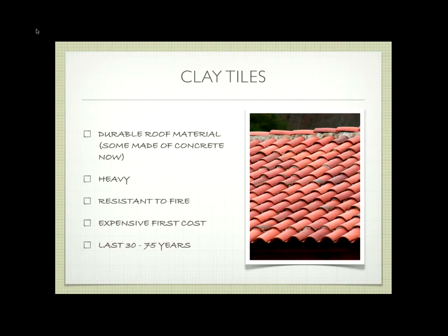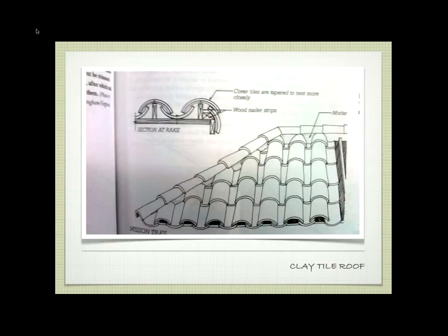They're very heavy, though, and that's something to be aware of. You have to engineer your building to withstand the loads that are there. They're resistant to fire. They are also expensive in the beginning, not as expensive as slate, certainly, but they're still more expensive than an asphalt shingle roof, for example. But they're going to last 30 to 75 years, which is a big benefit. So you're not going to be re-roofing as much.